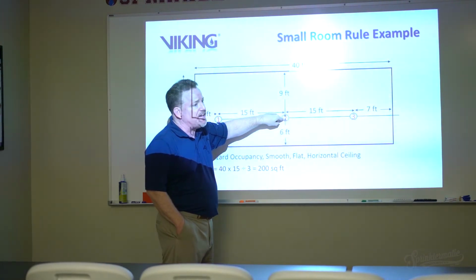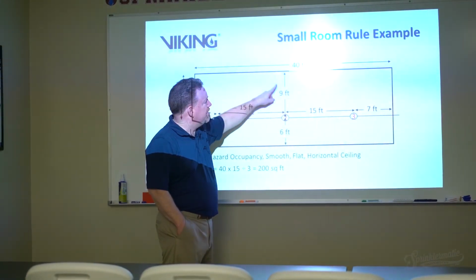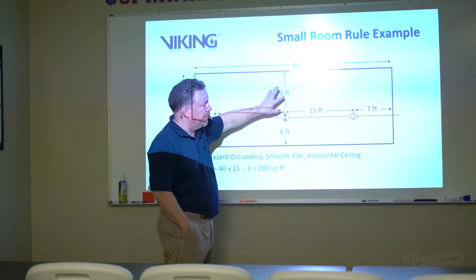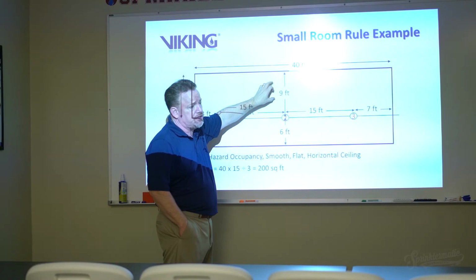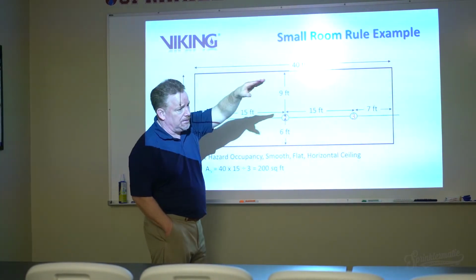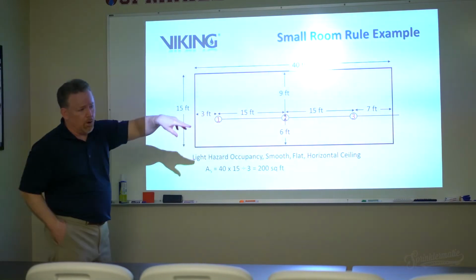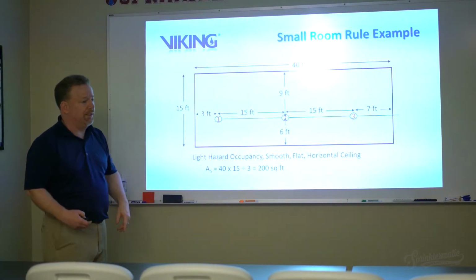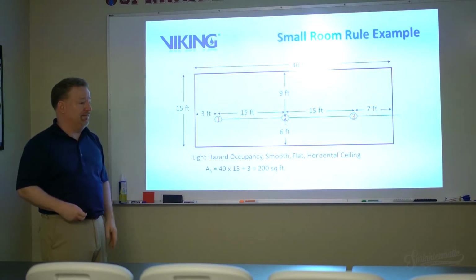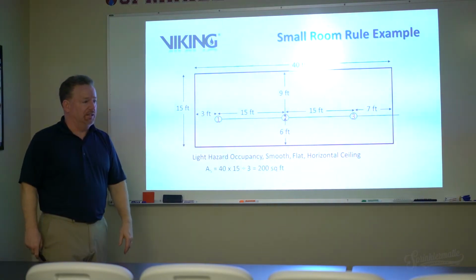It's going to slow it down a little bit. Yeah, because it's not going to respond as quickly. You would have a quick response sprinkler, but it's going to slow it down a little bit. Okay, and that's why we say all the openings except one 3-foot opening has to have a lintel, because we want to collect the heat up at that level and not let it escape.